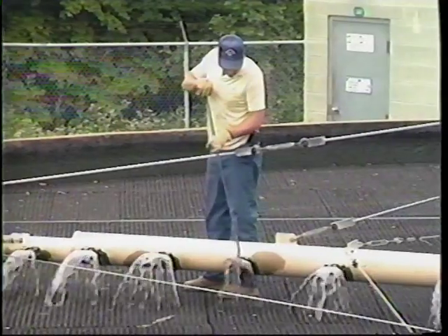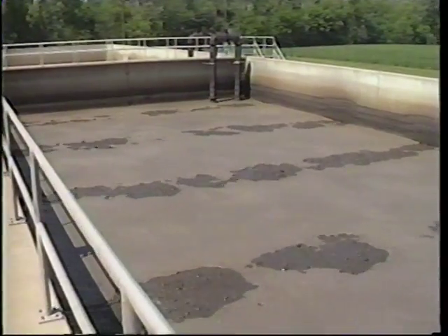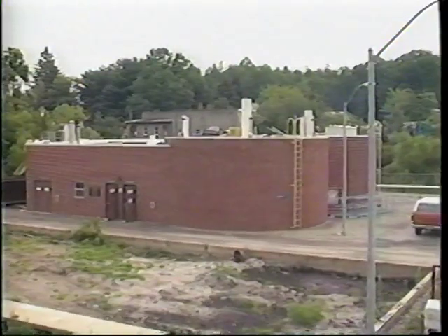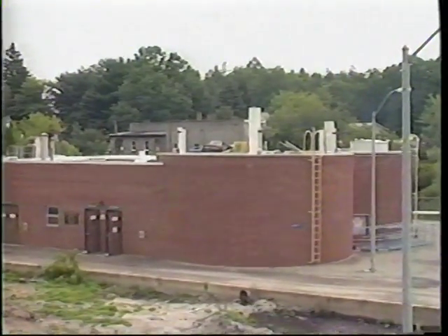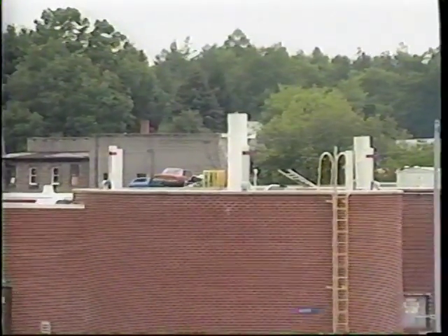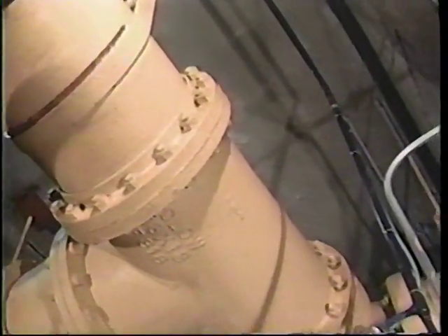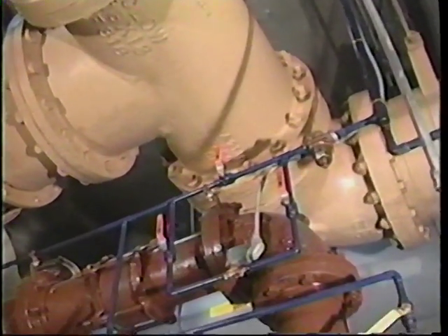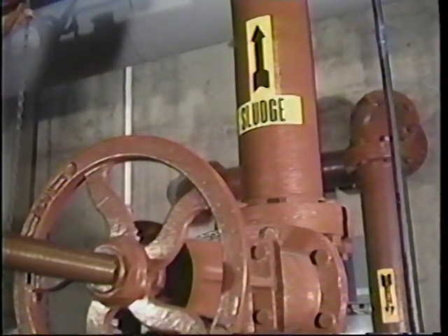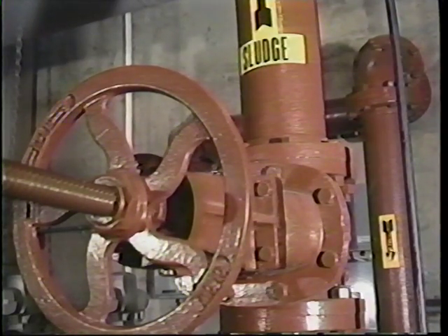Disposal of the floatable solids can be a problem as well. In many cases, floatable solids are placed in an aerobic or anaerobic digester. These solids present a particular problem in anaerobic digesters because they increase the depth of the scum blanket, resulting in the loss of valuable digester space. Some anaerobic digesters are equipped with a mixing capability, which helps in breaking up the scum.